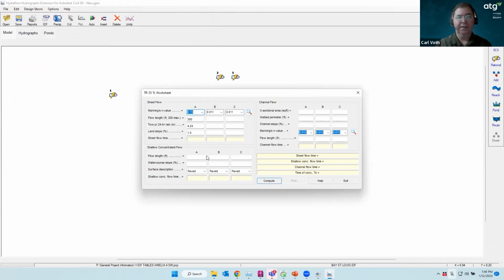All right. Now I still have 900 feet left of what's referred to as shallow concentrated flow. A good way to imagine this is if you've been out in a big field during a rainstorm or right after a rainstorm, you can see where the water is flowing down through the channel, it's actually kind of coming up out of the grass a little bit and turned into a small, not really a river, but just where you can see the water up above the ground.